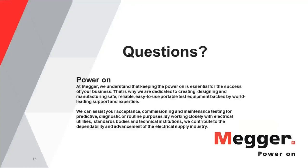That's when you need to use another type of equipment for cable testing, and that's why these other tests, such as tan delta or very low frequency tests on cables, have been developed for diagnostics. Also, for fault location, you need a lot of energy to be able to create a fault that you can locate.